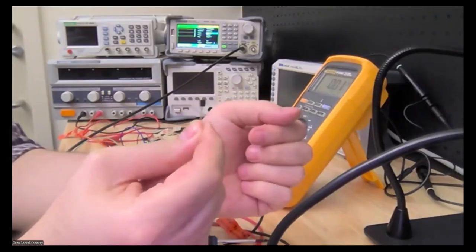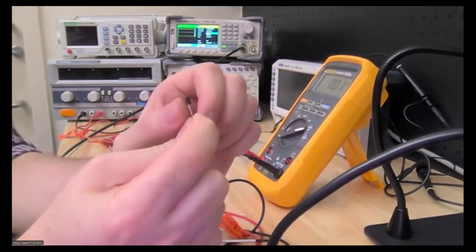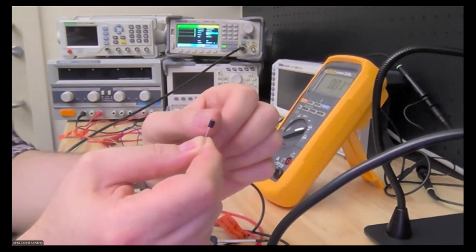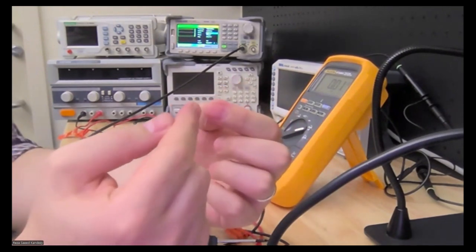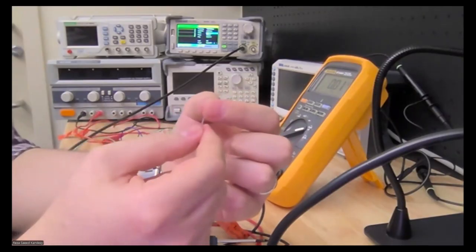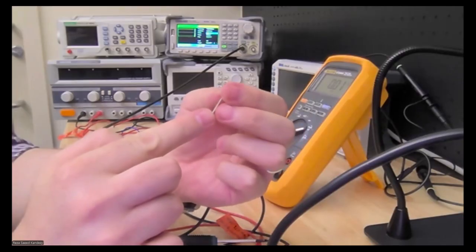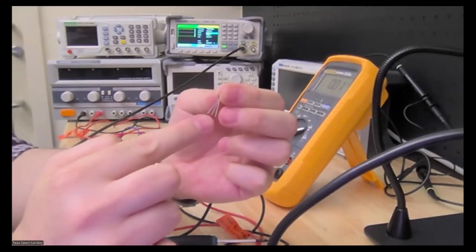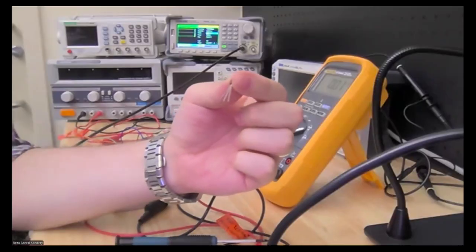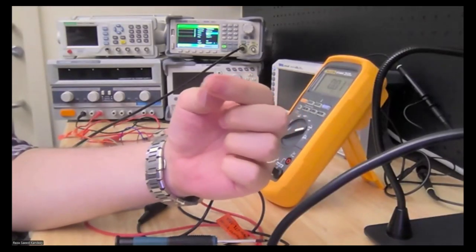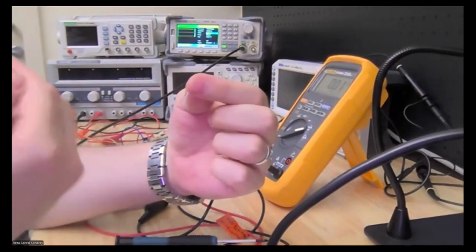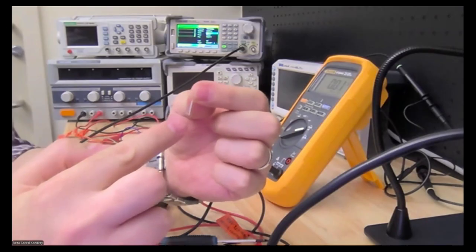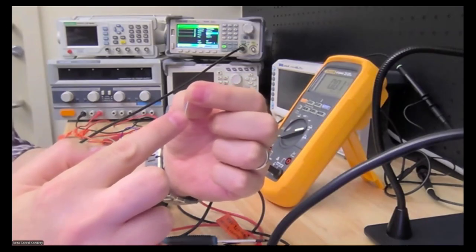Now, when you hold a MOSFET, one side of the MOSFET is a flat surface, which the model is marked on. When that flat surface is in front of you, the left pin is the drain, the right pin is the source, and the middle one is the gate. So when you want to connect them, remember the flat surface should face you. Then the left one is drain, the right one is source, and the middle one is gate.